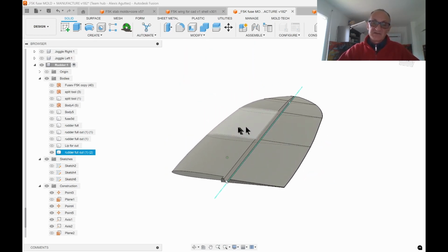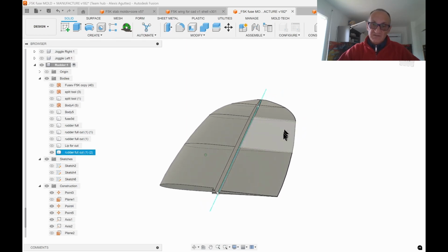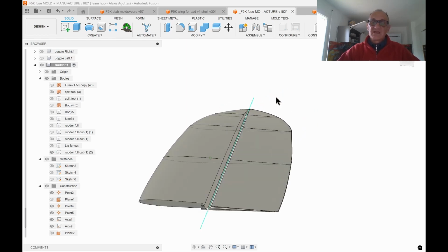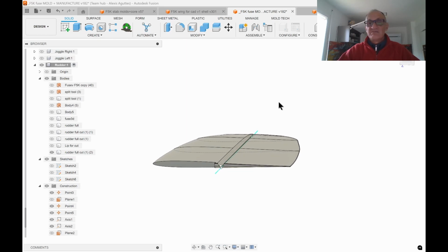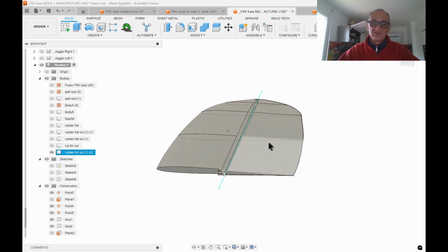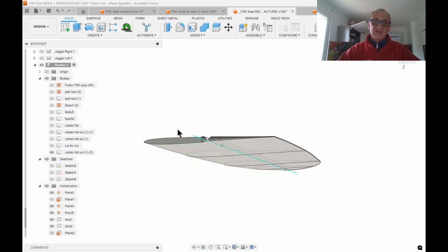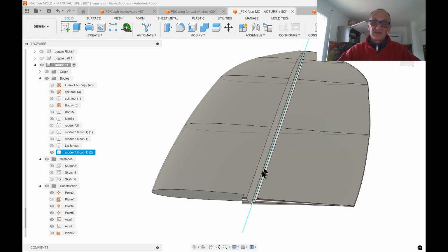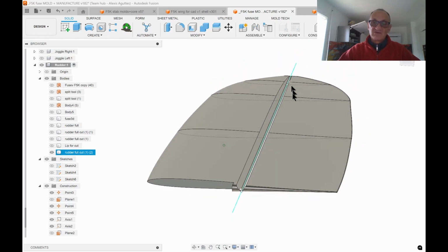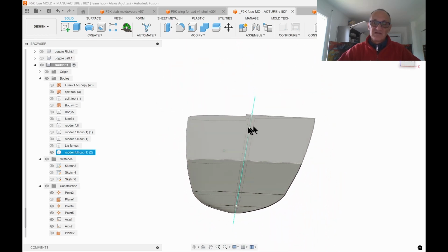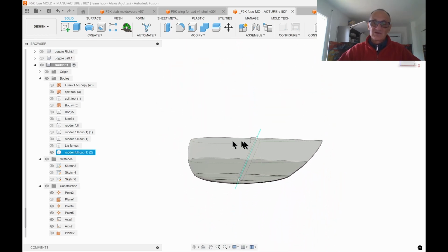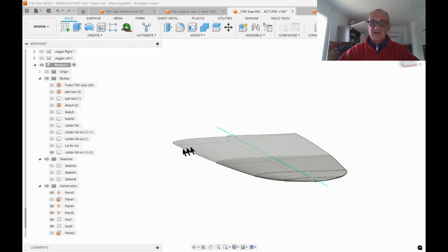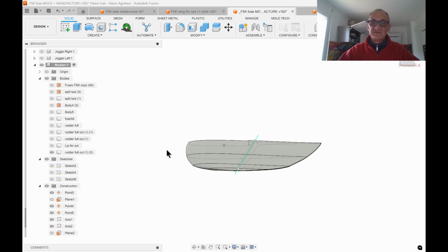technically it's not possible to mill this in one piece if you don't have a bed with some vacuum. If you are milling a block in the form of a rudder in a two-side operation, top and bottom, you are going to have some problem here because after milling one face, when you go down, the block and the core will not have enough strength to maintain and sustain itself, and it will collapse, and then the milling will not be accurate.